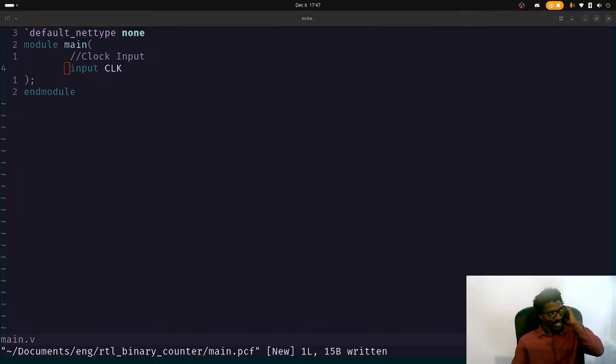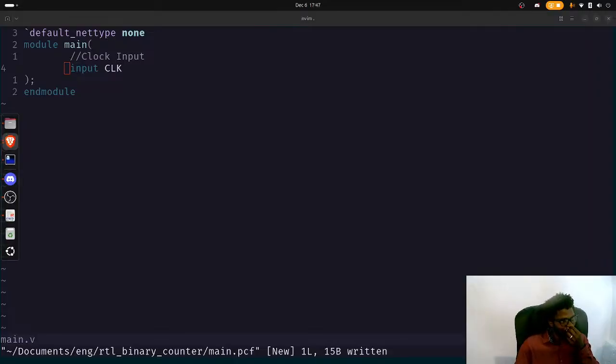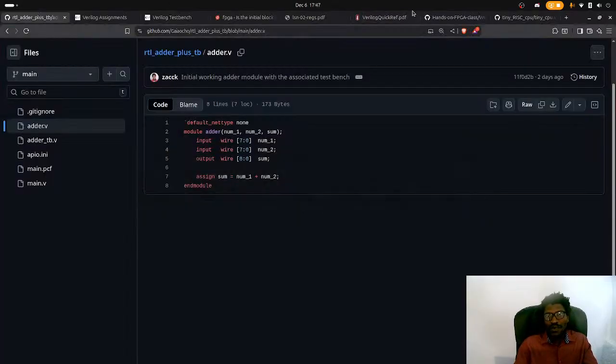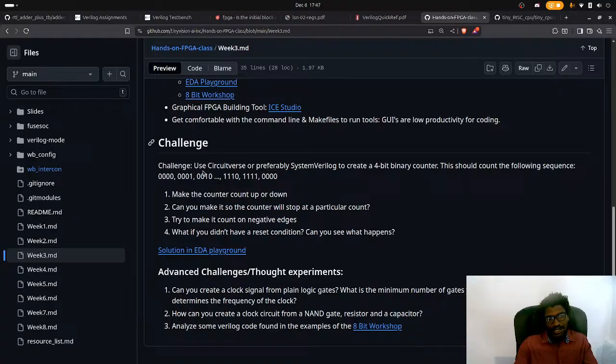And okay, so now what do we want to do? The next thing, let's think about it. We want to declare a 4-bit register, because look, let's look here. We want 4 bits in a register, and we can't use a wire because that's a bus. A wire is a bus. Wires versus registers. Wires are buses.